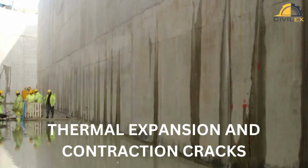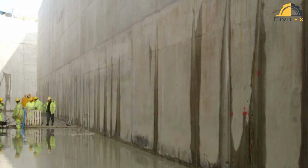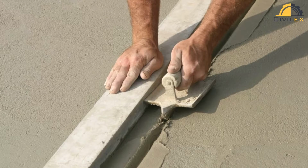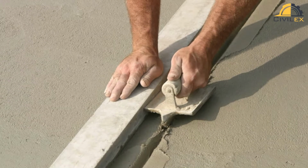Thermal expansion and contraction cracks. These are cracks that occur due to temperature changes in the concrete. When concrete is exposed to high temperatures, it expands, and when it cools down, it contracts. If the expansion and contraction are not accommodated, the stress can cause cracks to form. To prevent thermal expansion and contraction cracks, joints can be installed in the concrete to allow for movement, and the concrete can be reinforced with steel.